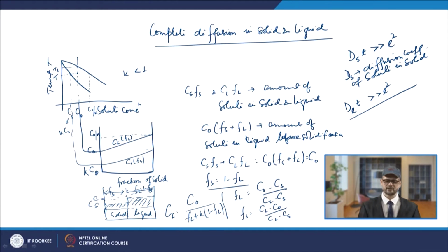So, depending upon the value of K, the equilibrium partition ratio, and the fraction of liquid, for the particular composition you can find the concentration of that liquid portion.